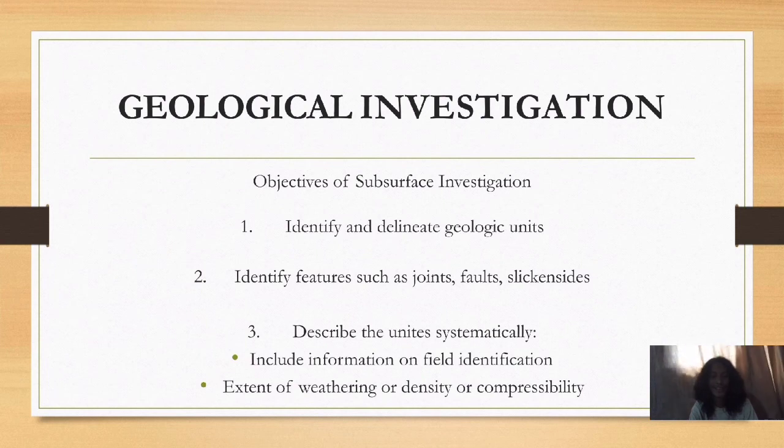Geological investigation. Objectives of subsurface investigation. Number 1. Identify and delineate geologic units. Number 2. Identify features such as joints, faults, and seismic sites. Number 3. Describe the units systematically, including information on field identification, extent of weathering, density, or compressibility.